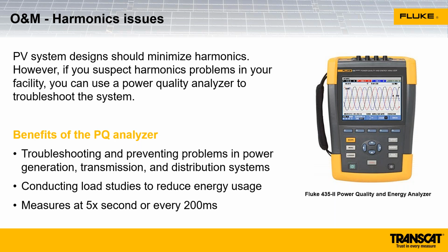Inverters have an operating voltage window and an operating frequency window. So if the utility connection goes outside that window, our inverter is going to shut down. And obviously we're not going to be able to produce any power if the inverter is off.